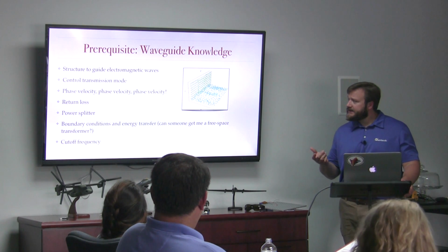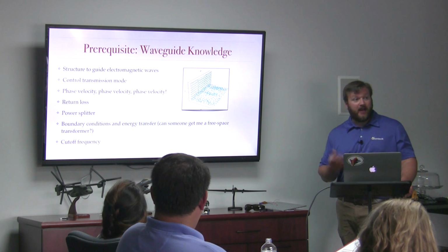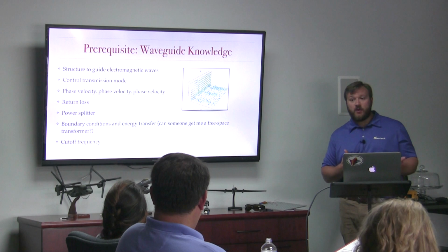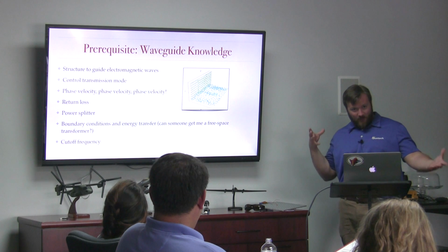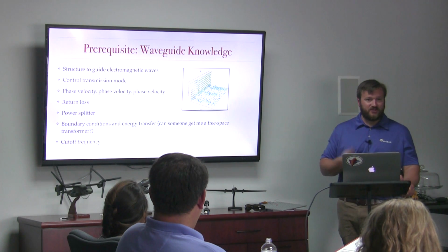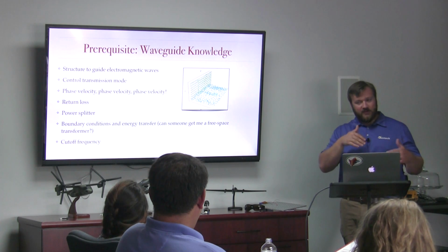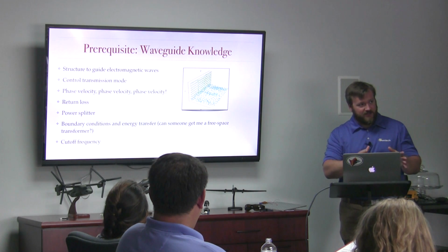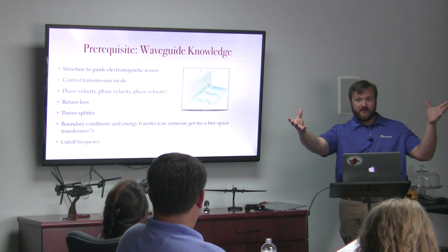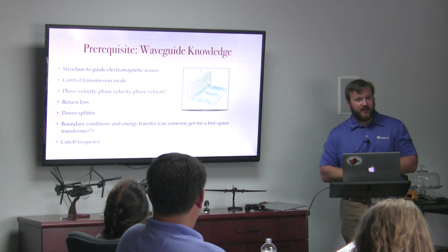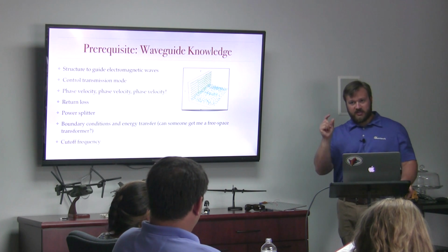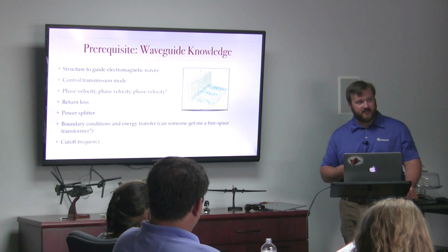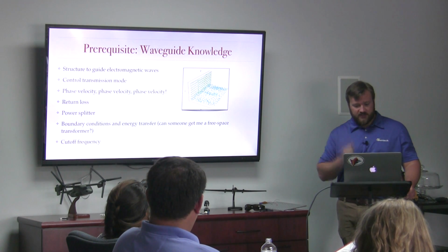Some other things that we looked at in the design were the boundary conditions. So we're going from one WR90 waveguide into a feed network that is a different cross section, into another cross section that is the radiating portion. So we have these boundary conditions going from one to the other. And you'll see on the back plate of the antenna, if you go down to the machine shop, that there are different tapers coming down, feeding the radiating waveguides coming out of the antenna. That's what that's compensating for, being able to transfer the maximum amount of energy for the aperture that we produced. And the actual slots in those apertures are about the same as the radiating slots themselves as far as their shape, but their orientations are different.